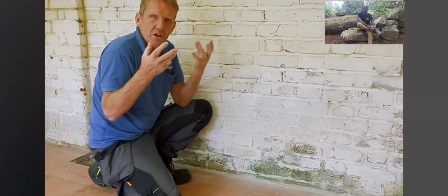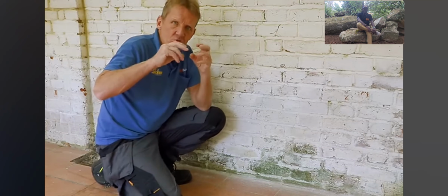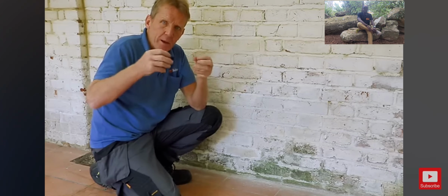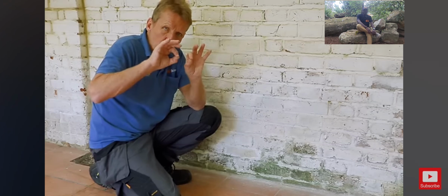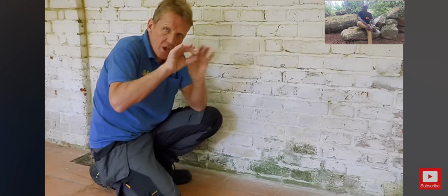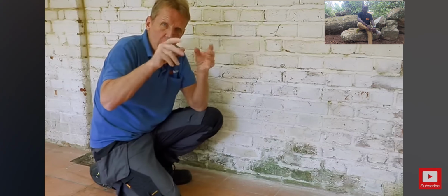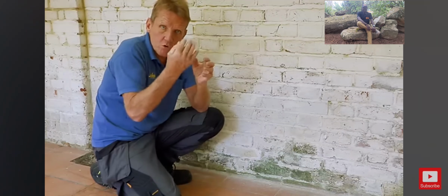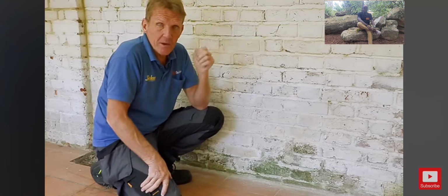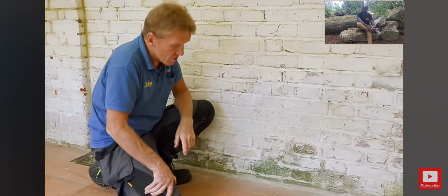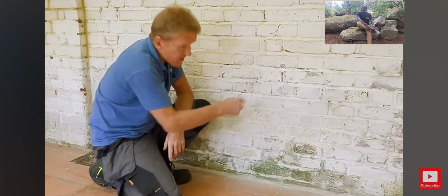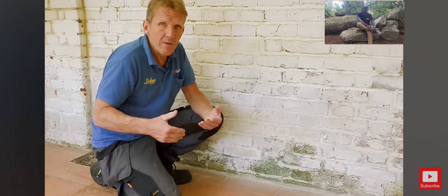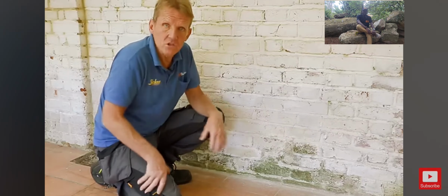It's a kind of cream, a kind of chemical that goes in, and it reacts with the damp. It's leached out as the damp comes to act on it, and it waterproofs all the capillaries. All the tiny little holes in the mortar courses are filled up with this glass-like material, which just stops the water from rising up. I've used it on many occasions, and it does work. So very simple. We just drill it and we fill it, and after a few months you'll notice that the wall begins to dry out.